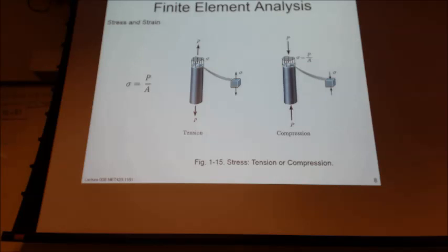Okay, we're going to say that the material maintains its orientation before and after the loading, right? The cross section maintains its plane, and we're not dealing with localized distortions, St. Venant's principle, right? We're going to move away from those. As a reminder, for St. Venant's principle, to get away from that localized stress concentration, you have to move at least the width of the material away from the edge.